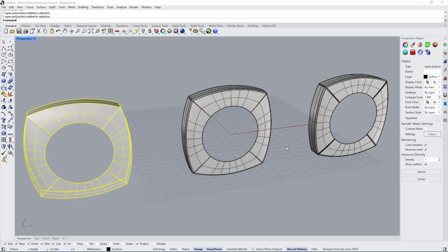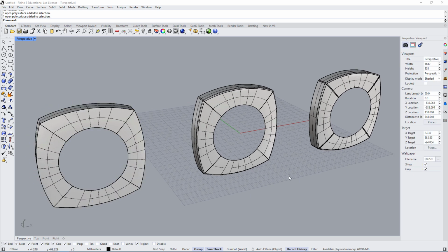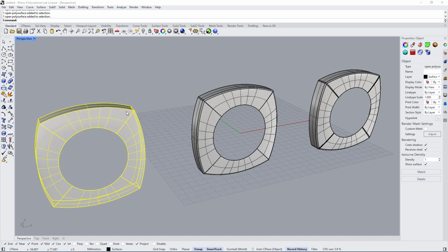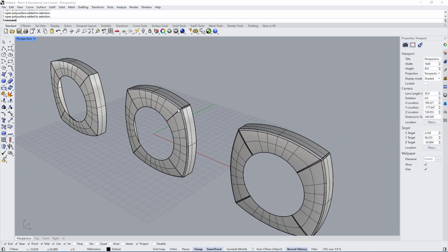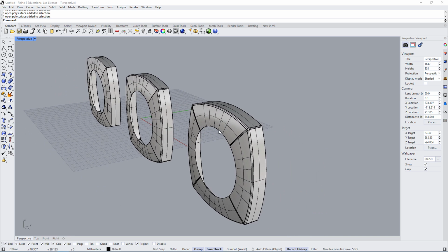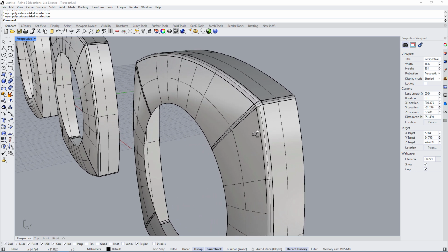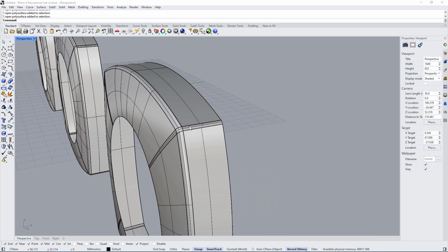Let's use this simple example to talk about parametric design within Rhino. In previous videos, we talked about measure surfaces and how we can add a fillet edge to some of these surfaces. And if we want to have a greater level of control, we can also use a blend curve between some of the surfaces. We can adjust where we trim the surfaces, and we can build curvature continuous transitional surfaces